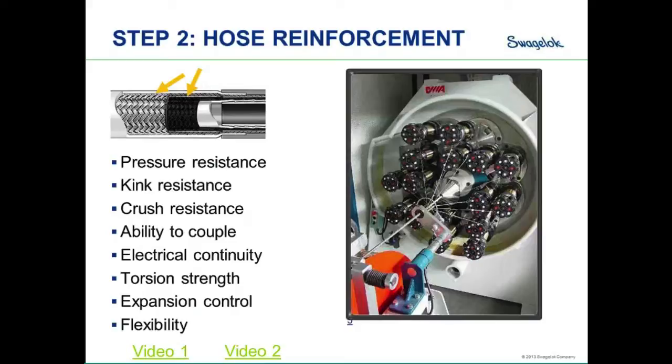So, to again go back to the garden hose, if you take your garden hose and you start to see it bending, and when it bends beyond the point of the minimum bend radius of the hose, it starts to flatten out and starts to oval out. So really, in a hose design, you want to keep that core tube round. If you can keep that round, it's going to be strong. The second it starts to lose its shape, it becomes vulnerable, and it can't handle the weight. Okay, so that's really what the intention of reinforcement is, to allow for flexibility.